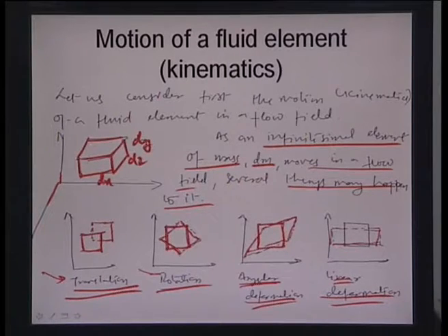That means because of volume continuity, if you increase the length of the block by pulling it, the area of cross section will definitely decrease. So, there are 4 different kinds of kinematic states that this block can have while moving in a fluid volume. One is translatory, another is rotary, as you can see here. Third is angular deformation, where you are trying to compress the block and make it from a square into a parallelogram, and the fourth is linear deformation, where you are trying to pull the block and reduce cross section and increase length. Okay.